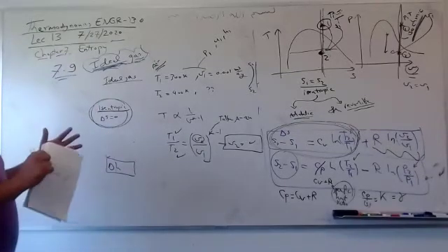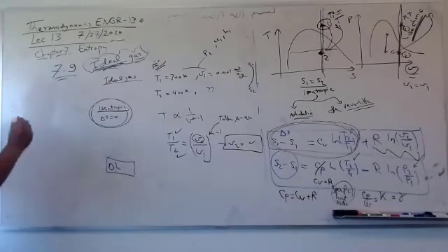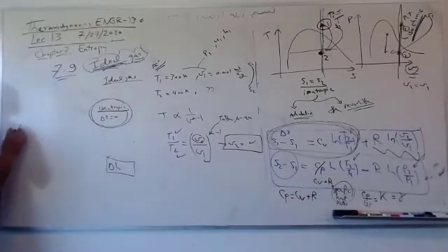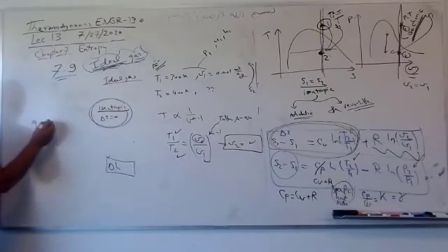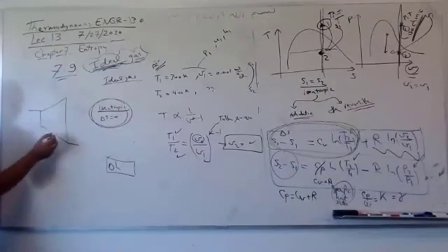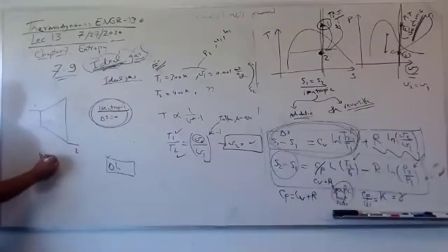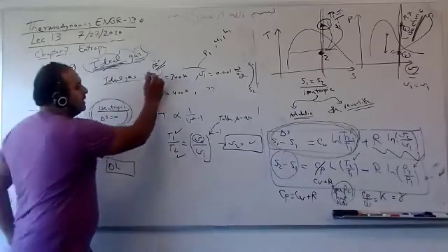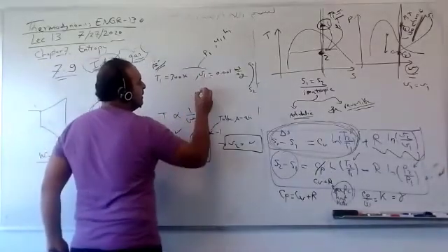But when you have a problem, let's say you want, for example, to get maybe Q minus W, or actually no, if you have a turbine, you have energy coming in, energy going out. This is a turbine. This is 1, this is 2. So you want the work done, it's delta H. Work per unit mass is delta H. So we want to get delta H.